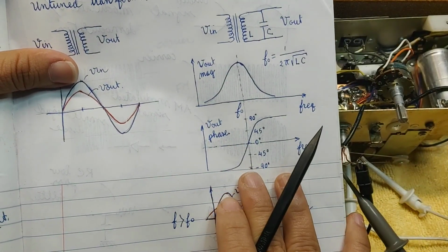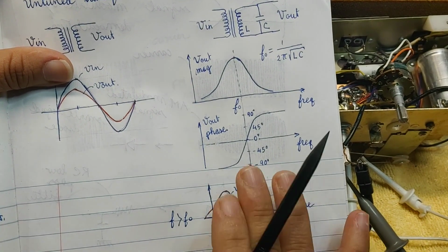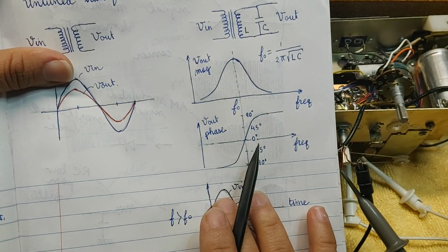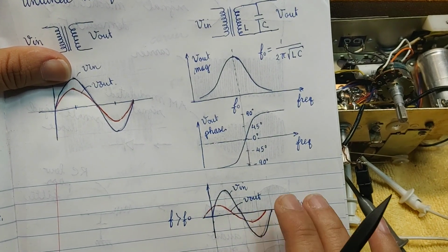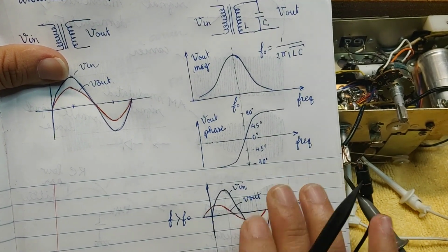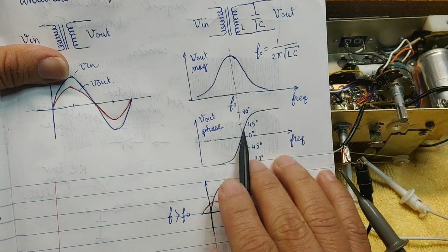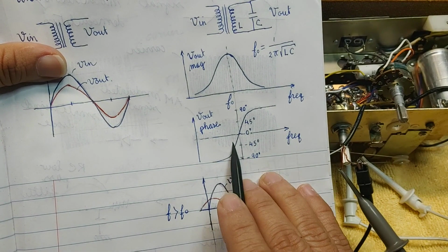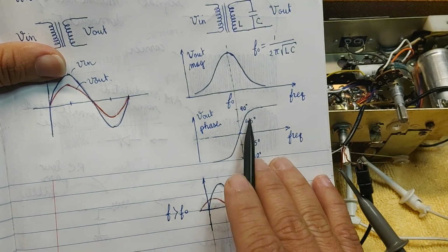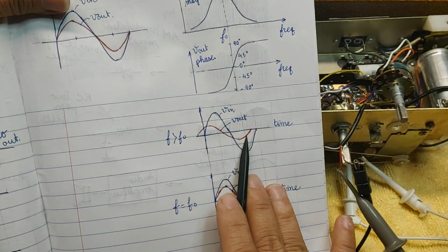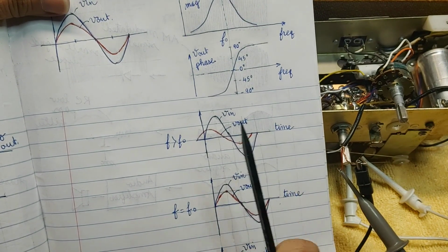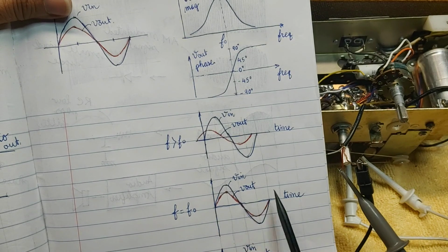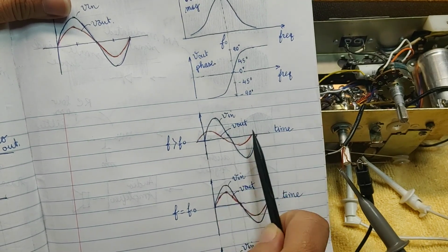The FM detection circuit in this radio employs the variation of the phase when the frequency changes to convert the FM intermediate frequency to the audio signal. So it's based on this variation. When the frequency changes, the phase of the output changes. You can see the red signal here, as the audio changes the frequency, goes back and forth compared to Vin.